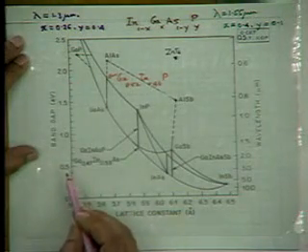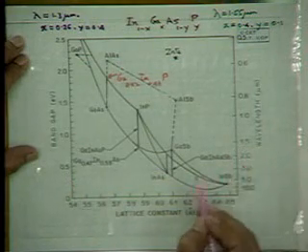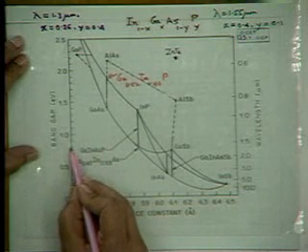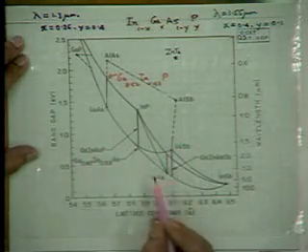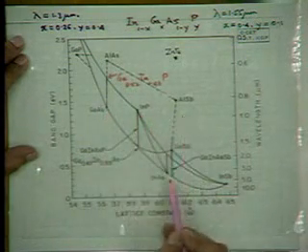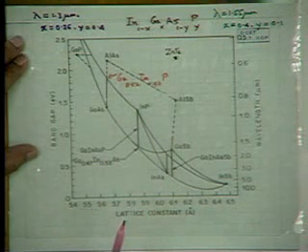If we are looking for materials with a specific band gap, we can take the horizontal line corresponding to 0.8 and extrapolate. And we find that the most common semiconductors, gallium arsenide, indium phosphide, they do not have the specific band gap required for fiber optic communication.